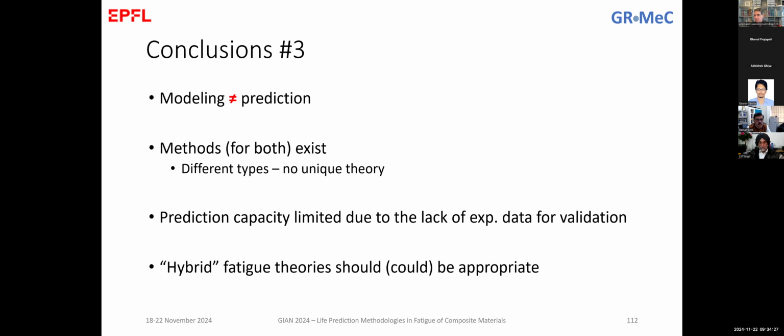I have one question here. You have shown, for multi-axial stress states, one of the failure criteria we can use, where the denominator can be a function of the number of cycles and other variables. There are people working on energy-based theories also, as well as some theories based on the fatigue master curve. So as per your experience, which gives us a better comparison with respect to experiments?